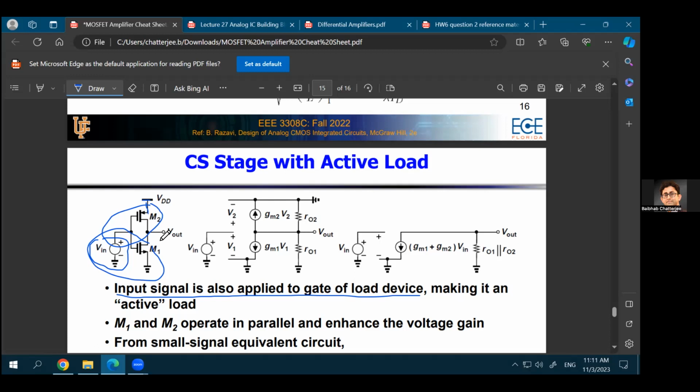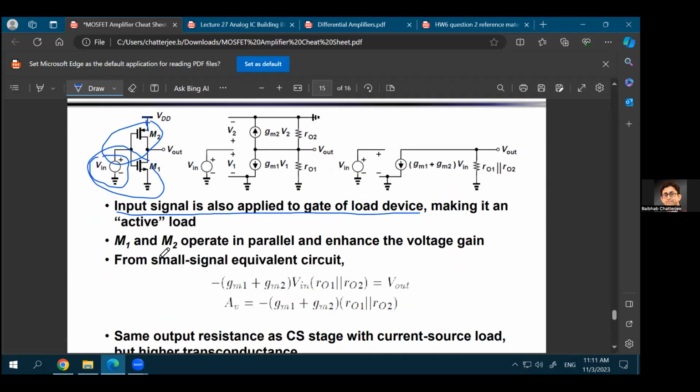And if you can use superposition theory, you know that you can increase the amount of signal at the output side. And that's what happens here, that here the GMs get added together. It's a superposition. Your GM, which is basically the AC current that you see at the loads, will be a superposition of the currents. It means that the currents will get added, and that means the GMs will get added. The transconductance will get added. And the ROs definitely will come in parallel with each other as in the previous scenario. So this will be the gain when you are doing an active load.